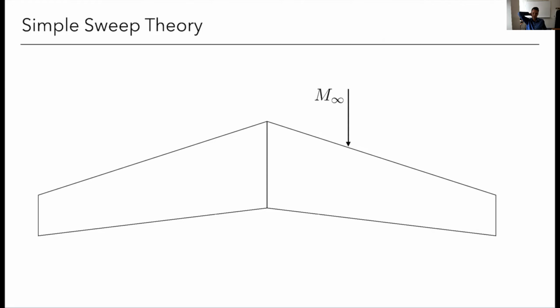They delayed publication, and they finally did some experiments where they dropped these swept projectiles and showed that indeed you could fly, or drop them, much faster at these higher Mach numbers without incurring this drag rise. So it was ultimately vindicated, and right about the same time, they realized that this had also been developed in Germany. So here's the basic idea, and then we'll try to get some intuition behind it.